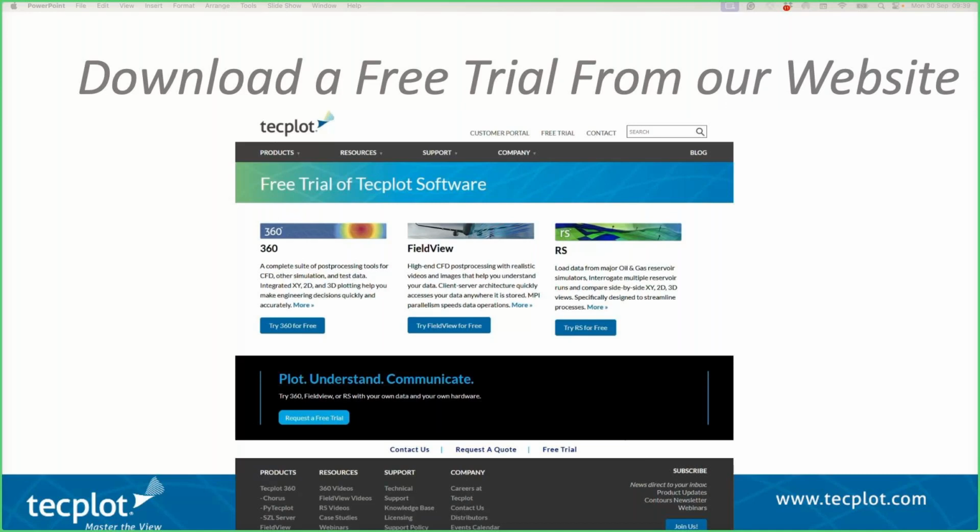One question. I think with the time, I actually have a question too. I don't know how much you can say. So the SZL format, subzone load, right? Yep. So you're accessing different parts of the domain. Yep. Is FieldView doing something similar? How do you guys think about that in FieldView volume data? So FieldView has a similar technology, but the way FieldView uses it is you actually have to load the full case once, and you'll be writing an equivalent to the SZL format. But at that time you will be writing it to file and reusing it for any following times that you'll be loading that data set.